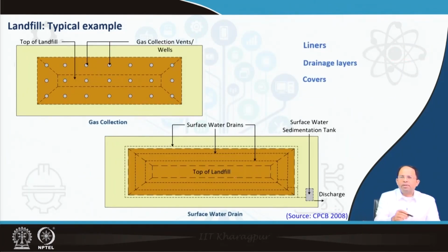Now, once the landfill profile is designed, then we can determine the placement of the gas collection wells. So this has to be predetermined. We can design not only the gas collection system, but also the drainage system and so on. So those layouts could be designed earlier based on the profile of the site as well as the section and so on. The top of the landfill, we can design the surface water drains, at what height we will design the drains. So this needs to be predetermined. The liners, drainage layers, covers, all can be predetermined when we design the entire landfill, and before actual operation all these designs need to be finalized.